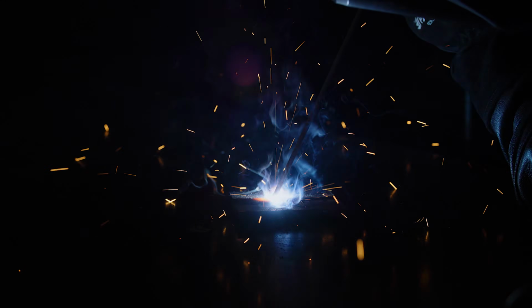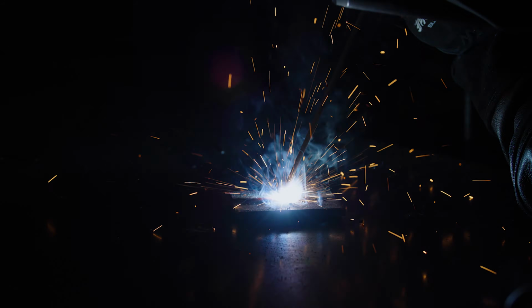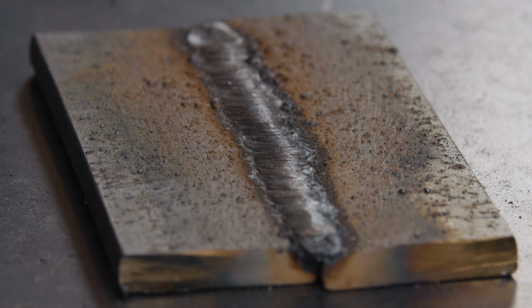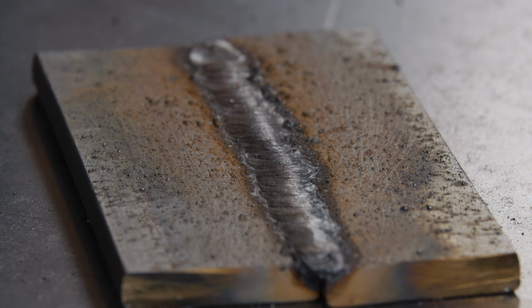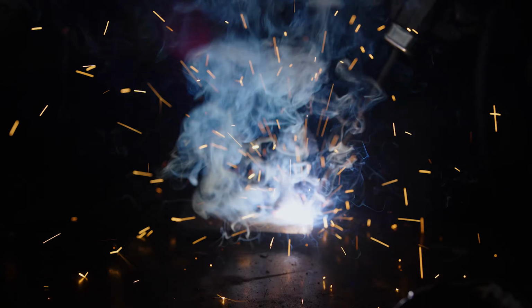Spatter is the small balls of metal that surround the weld once you're done. While welding, the sparks that spray from the torch or electrode often include little bits of molten metal, and these are left around the weld once they've hardened. They don't actually cause any harm to the weld, but it certainly adds to your cleanup time after you're done with the weld. Stick and MIG welding are the main welding processes that will produce spatter, and a lot of the time, it's impossible not to create it.